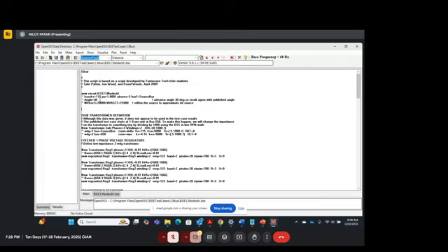So when you run power flow, you can just set this angle to be 0, and then you'll get VA at 0 degrees, VB at minus 120, and VC at plus 120. And then it's an infinite source, so they kind of stiffen that with a very high short circuit MVA.